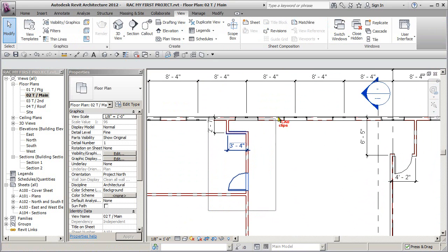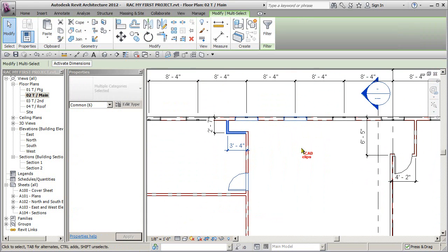So if you do a window box, it grabs everything within the box. You can still use your control button and do another window box, or you can individually select. After that first selection, you can hold your control button in and select more objects. You can continue using shift to select. You can shift and do a window box. So shift window box removes, control window box adds.